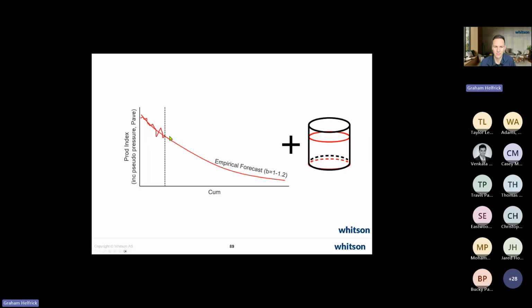And we're basically going to draw an empirical line through that to try to predict future productivity of the well. And when we couple this future productivity prediction with the material balance of how the pressure will deplete in the reservoir through time, we can really account for both effects to how the IPR will change and also how the well's forecast will change, even at different drawdowns.